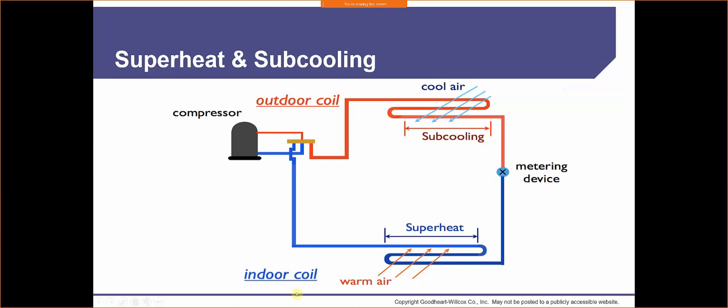We're going to still absorb more heat, all right? More heat's going to want to get into that refrigerant because heat travels to a place that is much cooler. We're removing heat. And that refrigerant is going to start to absorb more heat, more heat, more heat. And eventually we're going to get to the condenser outside, and we're going to have a 30-degree superheat. And we're going to wonder, well, why? Why do we have 30 degrees? And we're going to adjust our charge, and everything's going to be out of whack because we decided to put more refrigerant in there when it really didn't need it.